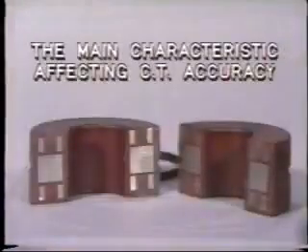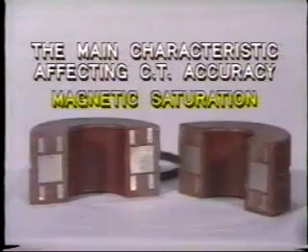In fact, for relay operation, we're really concerned that accuracy is good for much higher values of current, say 10 to 20 times normal full load current. Standard classification of CTs is based on allowing 10% error for current flow up to 20 times rated value. The main characteristic affecting CT accuracy is that of magnetic saturation.